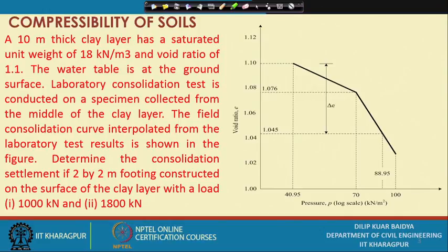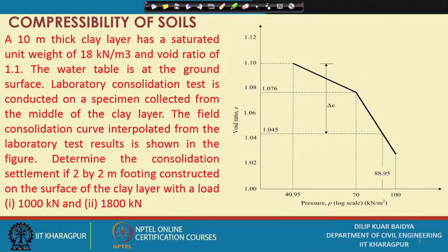But now, suppose we have an over consolidated soil, and the consolidation data, the e versus log P plot, is also available. For over consolidated soil, to make it simple, we get the e log P curve in two segments: present to pre-consolidation pressure one part, and pre-consolidation pressure to further consolidation another part.